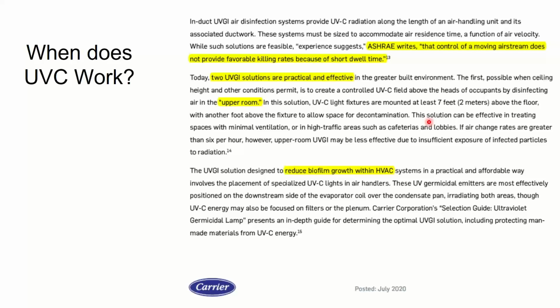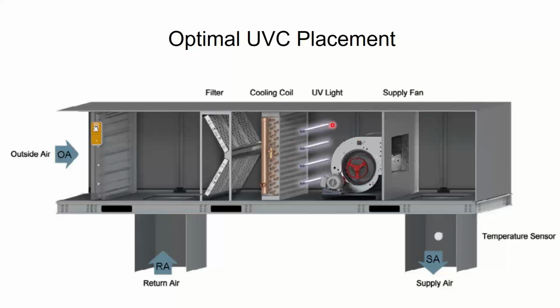But you could do that in the room and help out a little bit. If you're going to put them in your air handler, where should you put them? The best place is by the coil, because that's literally the only thing they're going to do a good job of cleaning. And they're going to do a really good job of that, but they've got to be by the coil.